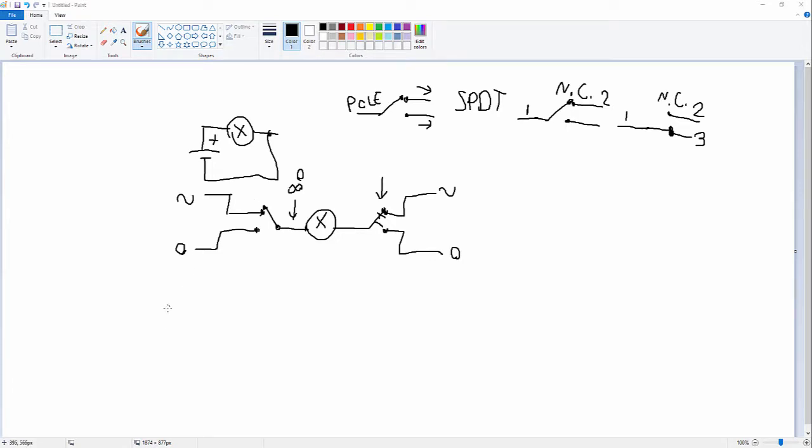So the other way is to connect phase. Again we will use the same SPDT switches, and now it will be crossed to another switch. Of course here it is not connected, this wire is going above the wire of the other switch, and now we have here the second switch, which will go like this to the lamp, and the lamp will go to 0.